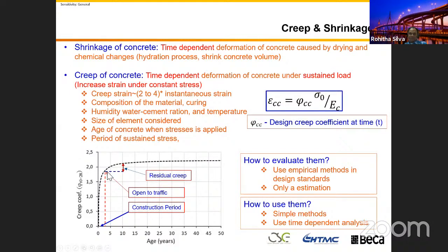The reason I am telling you this, when you design your bearing, when you calculate this, a lot of people don't understand the bridge construction. We install the expansion joint in the bridge at the end. Sometimes this is very hard to explain to the clients as well. When you calculate the creep shrinkage values, especially in the articulation, the creep will reduce the length of the bridge by a significant margin. So that length will affect your expansion joint size when you design it.